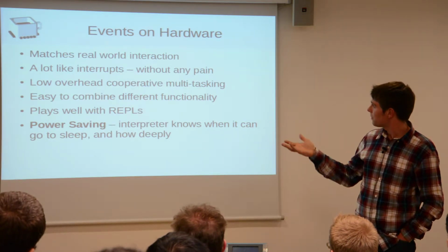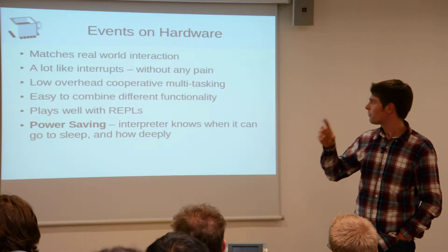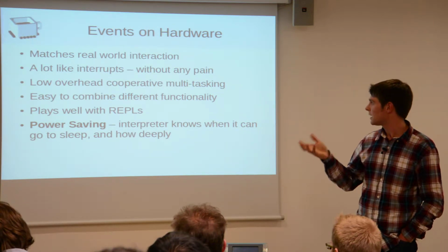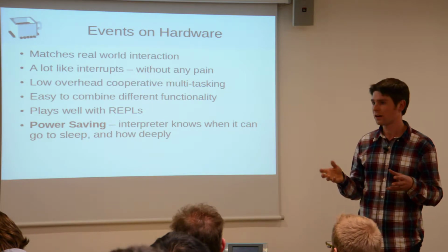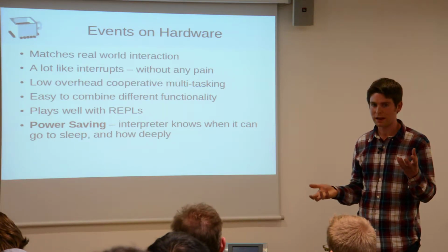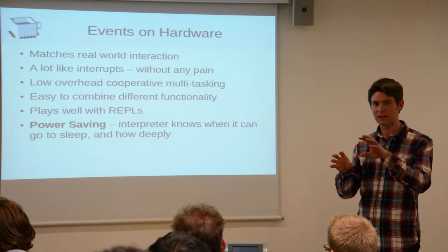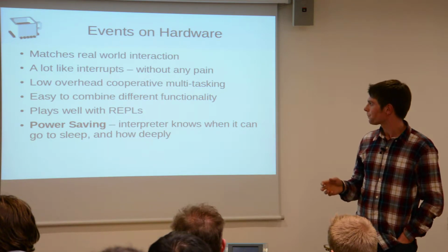Right, so because it forces you to write things in small functions executed one after the other, you effectively get cooperative multitasking, which is a really nice side effect. It makes it easy to put loads of different stuff together. The example of blinking an LED, you can just take that code for one LED and paste the code for the other LED in, and they're completely different. They don't interfere with each other at all.